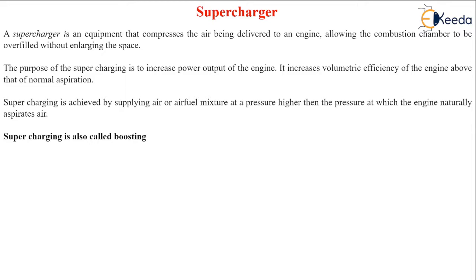As far as the definition goes, a supercharger is an equipment that compresses the air which is being delivered to the engine, which in turn allows the combustion chamber to be filled without enlarging the space to a greater capacity. As air is compressed, more amount of air can be accommodated into the limited capacity of the combustion chamber without any change in it. In short, the purpose will be to increase the power output of the engine.